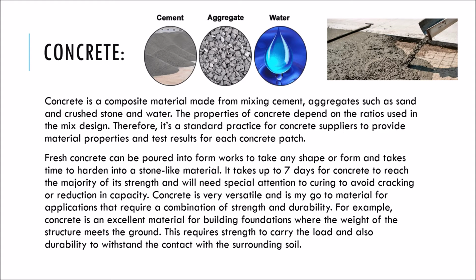Fresh concrete can be poured into formworks to take any shape or form and takes time to harden into a stone-like material. It takes up to 7 days for concrete to reach the majority of its strength and will need special attention to curing to avoid cracking or reduction in capacity.